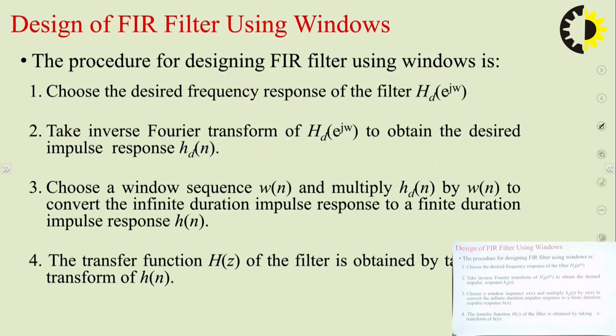Now, design of an FIR filter using windows. Here we will see how to design an FIR filter using the window technique. First of all, we choose the desired frequency response. Then we take the inverse Fourier transform to get the infinite duration impulse response. Then we multiply it with the window function to obtain the designed filter impulse response, and then we obtain the transfer function by taking the Z-transform of the impulse response.